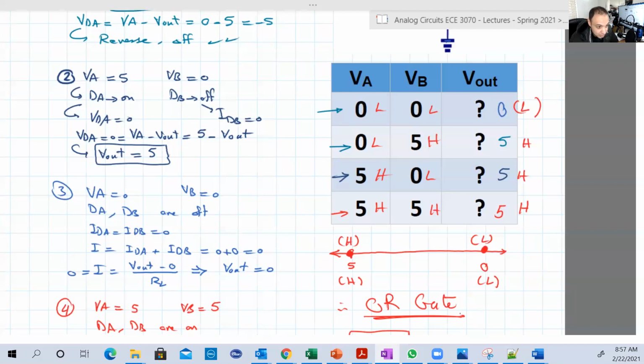Okay, and we're gonna see more examples when we explore another application for the diode, which is the rectifier, in which you usually have very high input voltages, and the output is equal to V input minus VD. And when VD is 0.7 and the input is, for example, 100 volt, so 100 minus 0.7 is 99.3. And if you consider VD is very small, I mean, if you consider VD is 0, it will be 100. You just neglect the 0.7 difference, which is the same basically. Okay, so that's a very good introduction for the ideal voltage model.